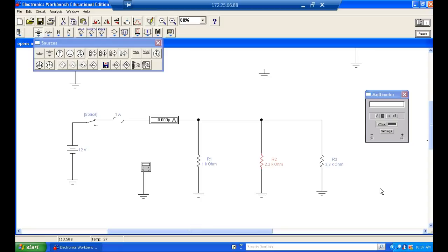Because of this reason, we can do what? I can unplug my Christmas lights. My garbage disposal still works. But if my garbage disposal shorted, it would pop the breaker, and I would lose everything on that electrical branch.